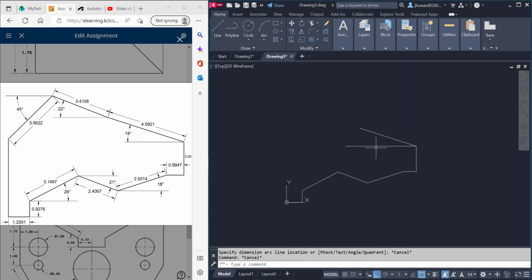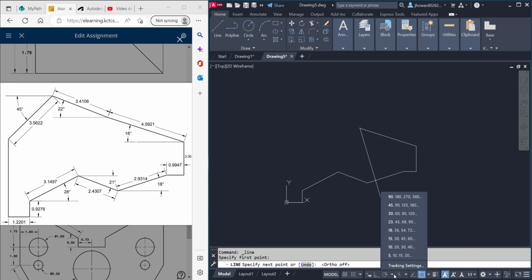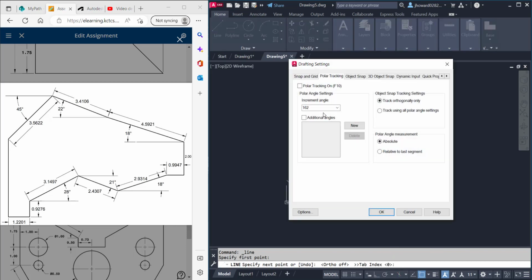18 degrees. All right, so then I get rid of that little line I was using. Make sure my object snaps on. I click right there at that button. And I'm going to go up another 22 off of that. So this one was what? Let's go here and take a look. The last thing we set was 162. And we're going away from that 4 more.